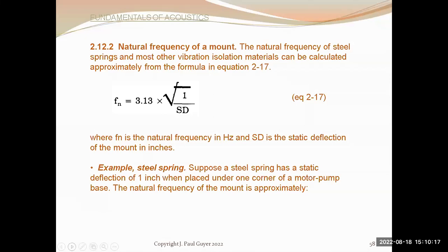A common situation in building design is a fan room with a fan in it. And you've probably constructed the fan room out of poured in place concrete or CMU block walls and so on, so forth. And that takes care more or less of the sound. But you are concerned about vibrations being transmitted through the building structure to the occupied spaces. And a common way that the vibrations of mechanical equipment like this are controlled is to set the mechanical device, whatever it is, a fan, compressor, etc., on a frame, which you then set on spring isolators.